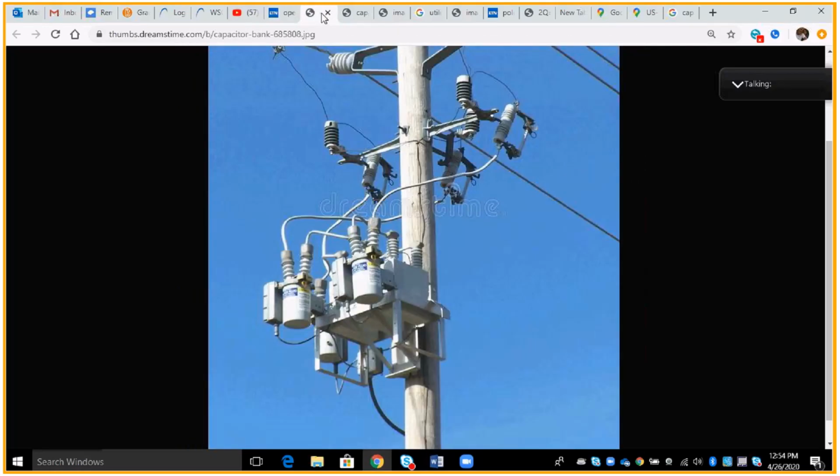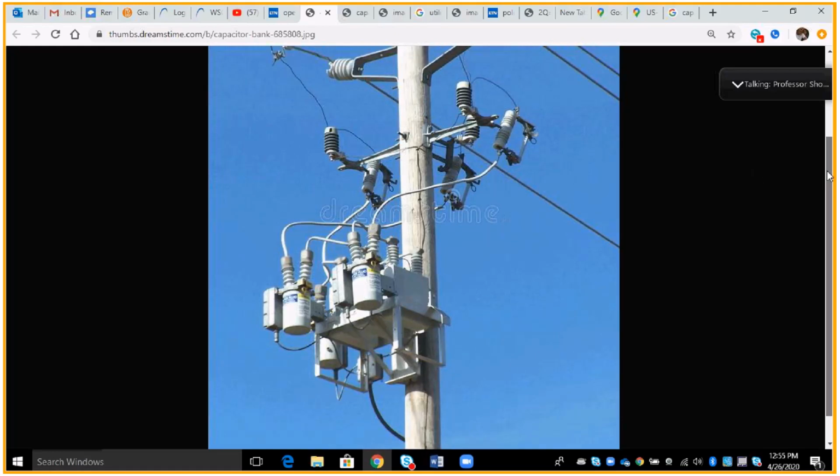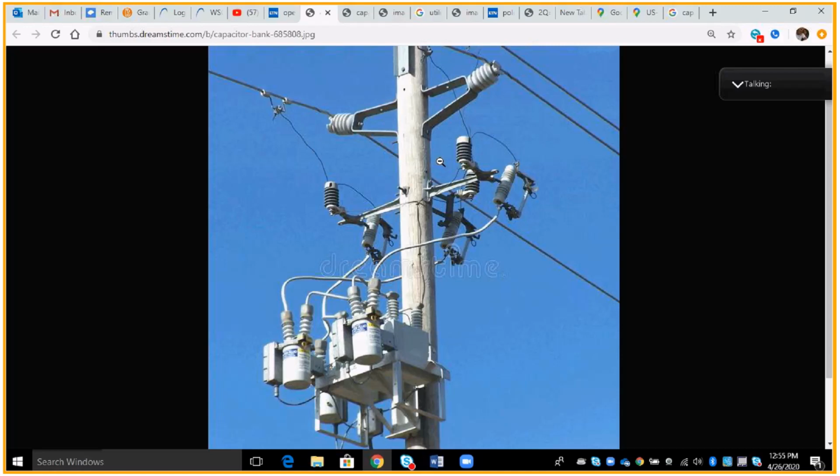This, for you gentlemen, they're going to be working on the distribution side, is a typical installation. Not all are the same. Different utilities have different designs and different structure to theirs, but they all have the same essential parts and pieces going on in it. So what we have here is, of course, our stirrup, hotline clamp, high side riser to the arrestor, and the arrestor to the switch. Then we have a low side riser off the switch, and they go to these vacuum bottles. Talk a little bit about those while we're on this picture.